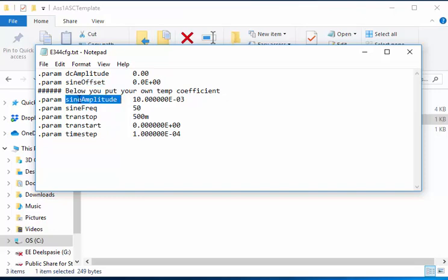So the noise that you have to filter as part of your design is specified by sine amplitude and another parameter that we defined, sine frequency. So by setting the amplitude here, we will check that you suppress this signal. So you need to set this to the appropriate noise amplitude level when you develop. So we've set this to be 1 degree Celsius. So if your 1 degree Celsius is equal to 5 millivolts, you need to change this to 5. If it is 55, you need to change it to 55 millivolts. So this is the amplitude. The sine frequency here is 50. That'll just be 50 for everybody.